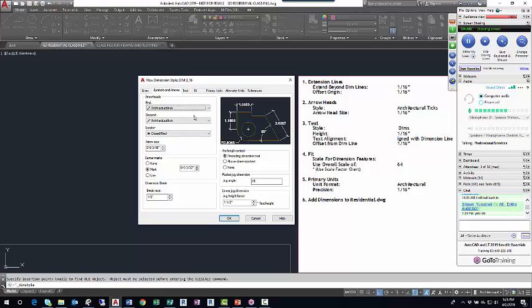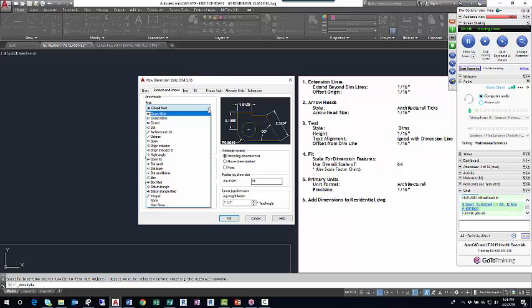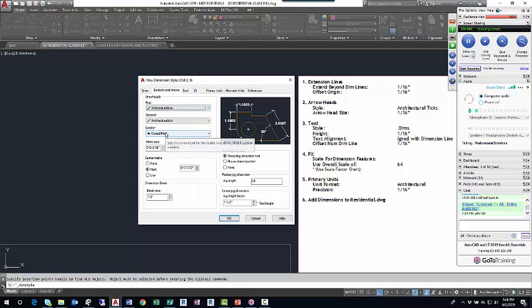However, if you're in an engineering role, if you're doing security engineering or fire alarm engineering, you might keep it at a closed filled arrowhead. That is more in keeping with an engineering drawing. If you're more architectural, use the architectural tick. But whichever you use, we're going to change the height of that arrowhead from 3/16 to 1/16. So we'll hit the down arrow twice.